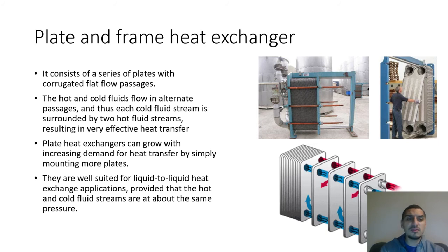There is one kind of heat exchanger which is being used but not as widely as the shell and tube heat exchanger, which is the plate and frame heat exchanger. And this is, as you see here, composed of just plates, and they can be added as many as you want. So you'll add a plate and then a plate, and they are very flexible in the sense of the ability of addition or removal of plates, and controlling the area of heat transfer. And of course it's easier in maintenance and in cleaning, because it's very easy to assemble and disassemble.